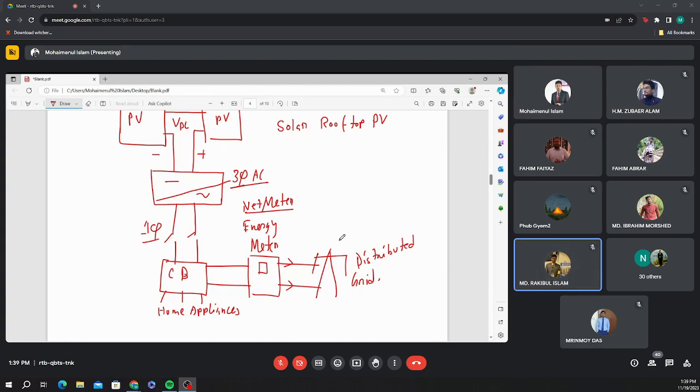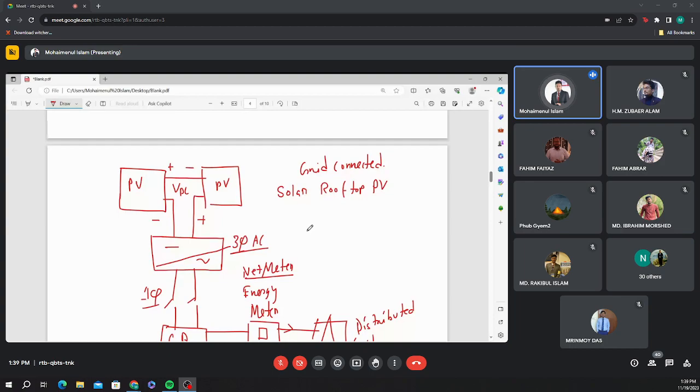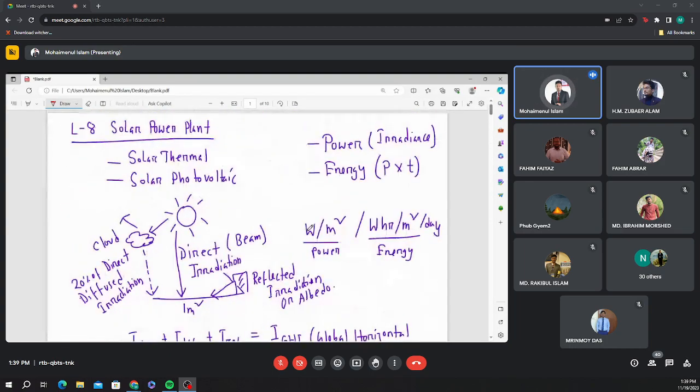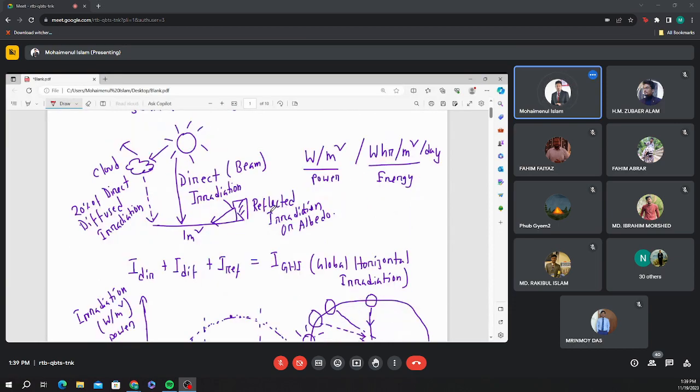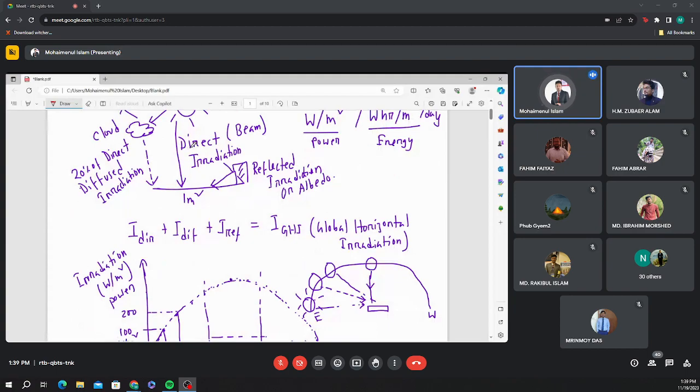Okay, so I think that's all for today's lecture. I'm just going to recap the whole thing. First of all, we are trying to cover solar power plants. It is in two types: solar thermal based power plant and solar photovoltaic based power plant. Before that, we covered what irradiation is and the difference between irradiance and the energy which is collected from the sun. And the irradiation has three components: direct, diffuse, and reflected irradiation.